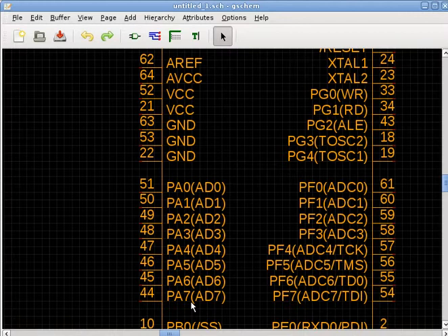For that sort of thing, you need to go to the ADC lines. ADC stands for analog to digital conversion. It looks at the entire range of voltages, like from 0 to 5 volts, and chops it down into 1,024 individual segments in this case, because it's a 10-bit ADC. So it can, to a certain extent, tell the voltage at the pin, but it's quantized, which means it can only go by 1/1000 of 5 volts, in other words, 5 millivolt increments.